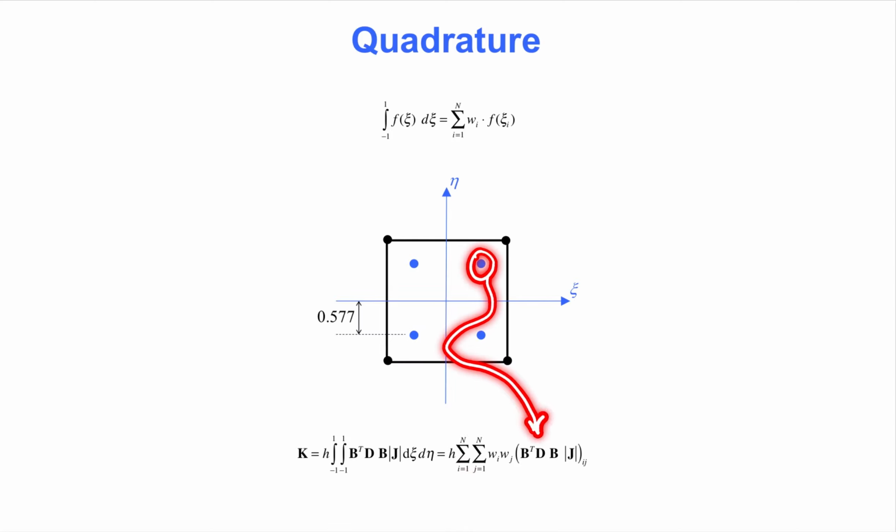in the figure above. It is rarely possible to obtain exact results with numerical integration. In addition to the use of shape functions that may not be exact representations of the displacements, the use of quadrature is another source of inaccuracy in the finite element method. For example, Gauss integration provides exact results for integration of polynomials up to order 2n-1, where n is the number of integration points in one direction.